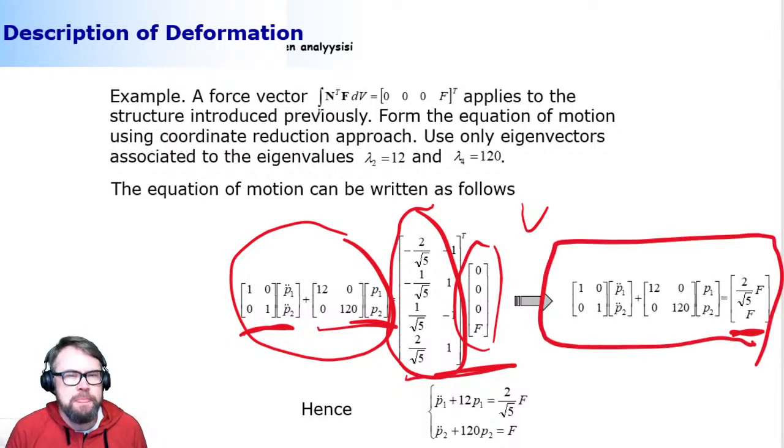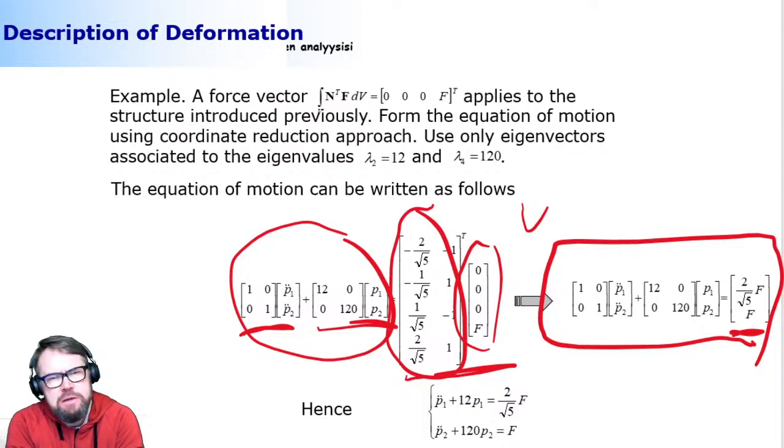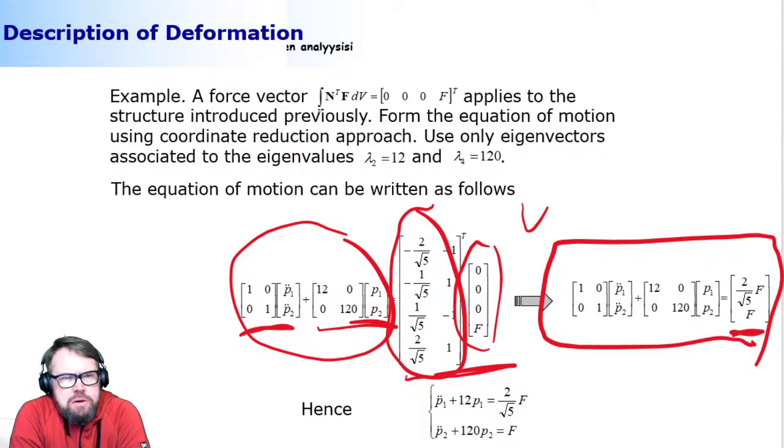So it's reduced. Not just reduced, but having another important mathematical feature, which is orthogonality. That orthogonality means that I can write the modal coordinate number 2 and solve it using nothing whatsoever about the first modal coordinate, and the other way around. And that can speed up the computation quite a bit because they have no dependency on each other. So that's how it goes.